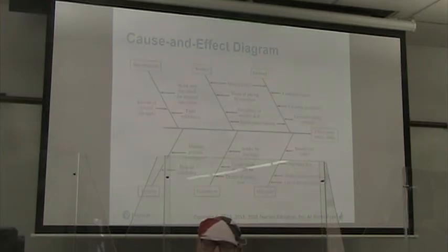All right, so here we see an Ishikawa diagram, or cause and effect diagram, fishbone diagram, whatever we want to call it. The effect that we get is we have poor solder joints. The different things that could go into that are the specifications, the workers, the method, the process, the equipment, and the materials.